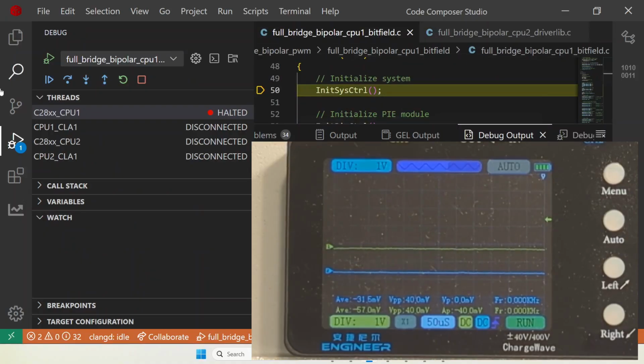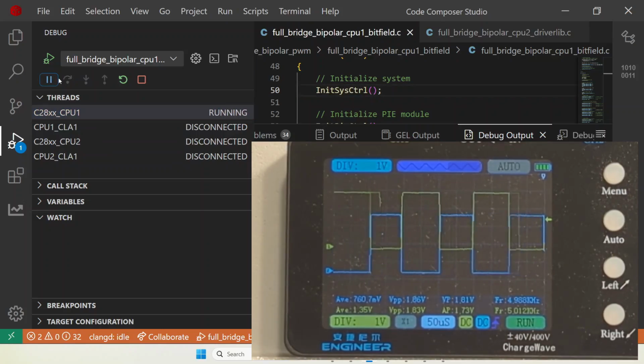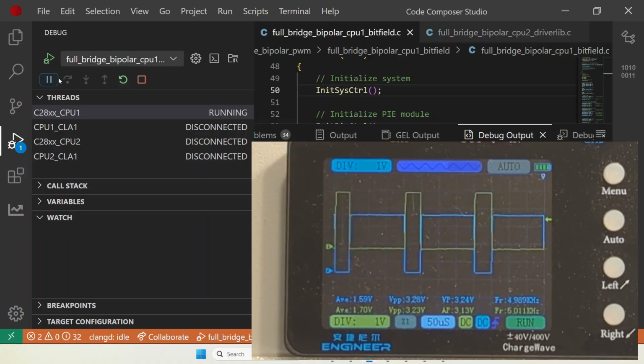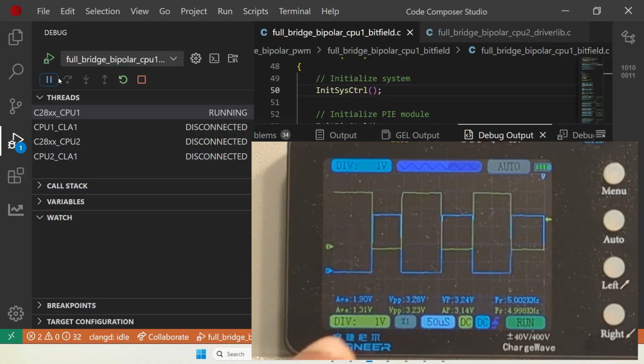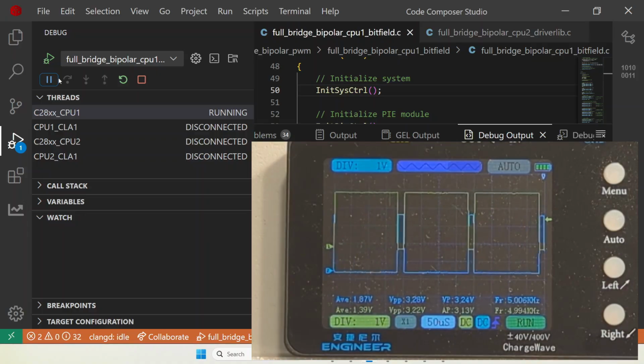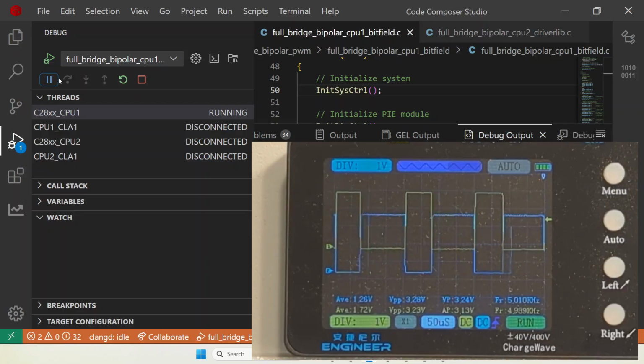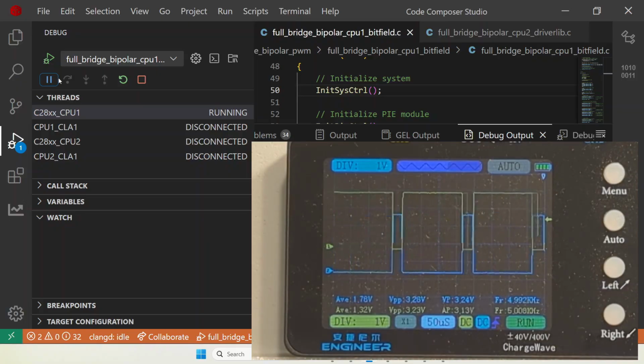And the project has been loaded, so all I have to do is click on it and click on the continue button. So now look at the oscilloscope waveforms, and you will see we got similar waveforms even with the half bridge DC to AC converter, right? So this is essentially the phase angle changing from 0 to 2 pi, as a result of which the modulation signal is a cosine waveform that is changing from -9 to +9. Right? So therefore, as it changes, the width of the pulses is going to change from the maximum to the minimum.